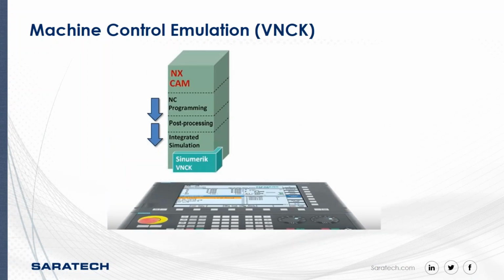Now in machine control emulation, the VNCK, it has the first three tiers of the integrated simulation, but it has a fourth tier on the bottom there. It's driven through the Sinumerik VNC control. So you take your G-code and then it drives it through the Sinumerik control that's actually on your machine. So it validates cycle calls, variables, and different things that's indicative of the machine control itself. So this fourth tier, if you have a Sinumerik control, is the complete simulation solution that Siemens can offer you.